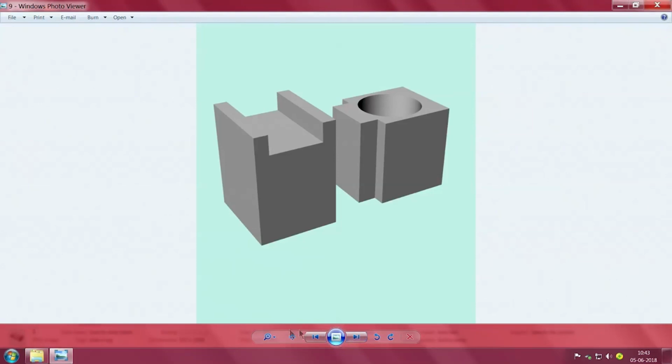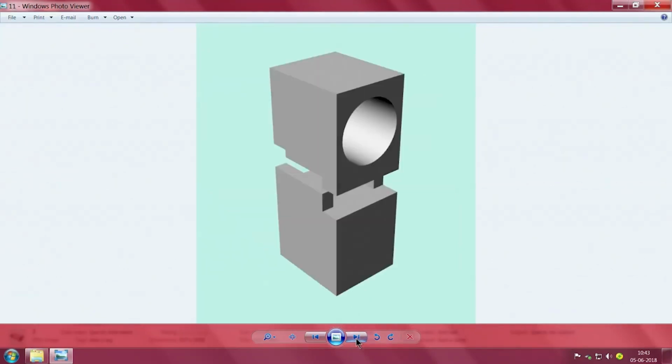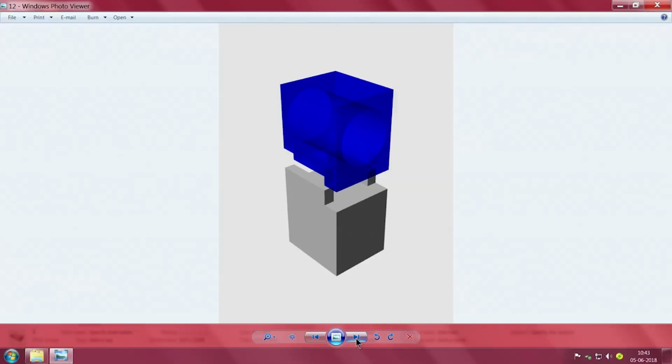Can you see here? Underneath there is a bore and there is something here. While it looks convenient, on further examination I found out that this bore should have been through, then only it makes sense. Now building this, the layers will build up automatically, building here also will build, but to support this topmost structure again a support thing will be required like this. So what to do? This has been added here. Can you see here a small cut has been given, and this has been added here so that it won't slide off. So now, one sits over the other like this.